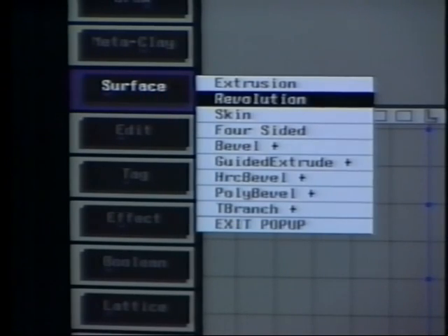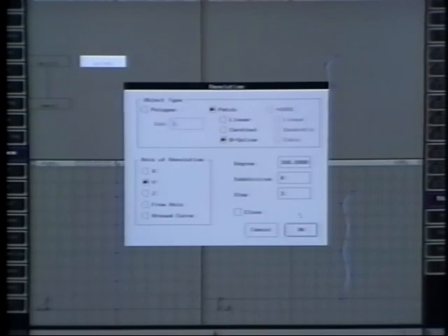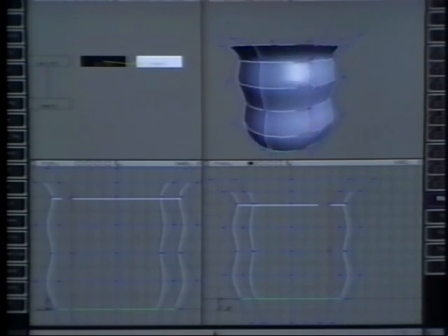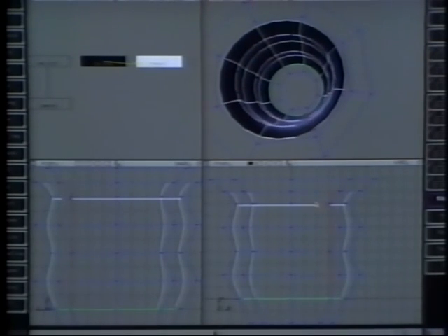One step at a time, just to make a surface that's closed in the U direction, we can revolve a spline, swept 360 degrees. Now the U direction lines of our grid are closed circles. The red edge flag shows the seam where the opposite edges of the surface meet.